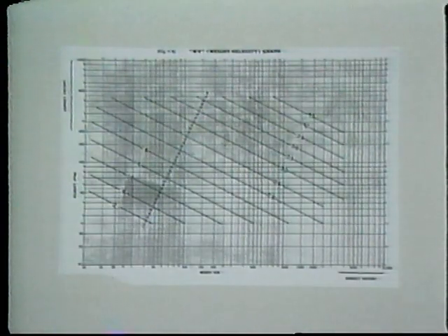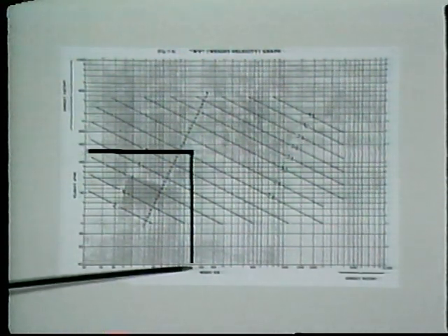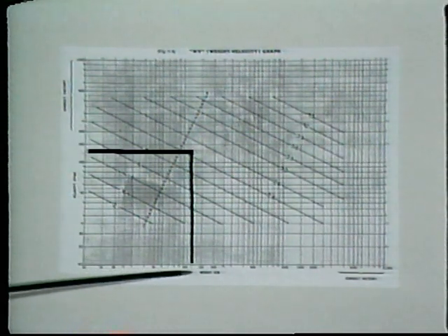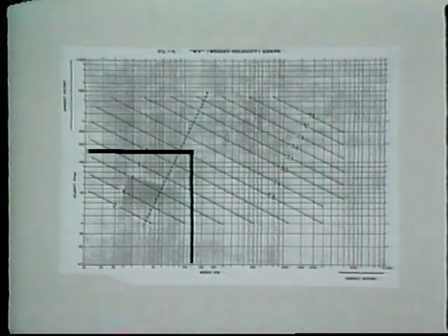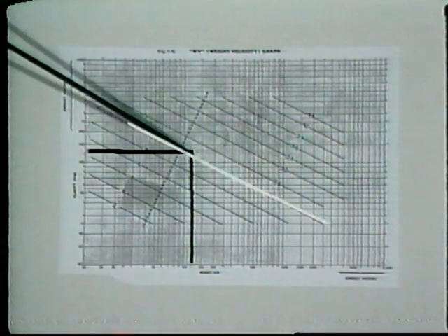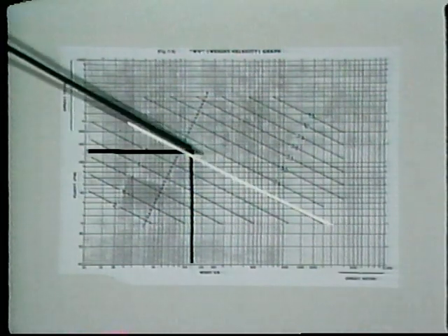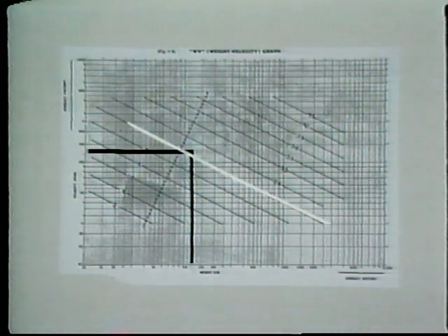Now you have to go to the WV chart. The maximum velocity here is 120 feet per minute, and the total weight here is 119.7 pounds. The two lines intersect here, which indicates that the cylinder must have a cushion rating of 22.4 to operate properly in your system.